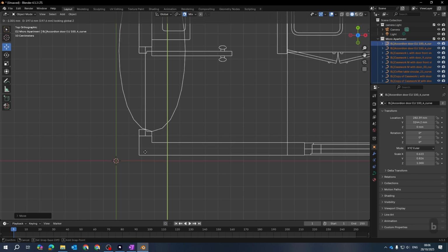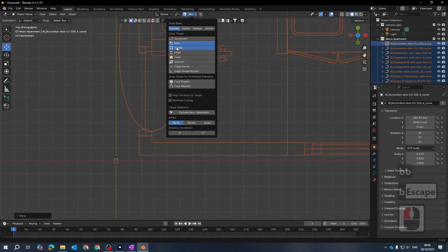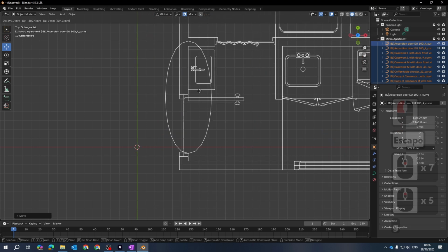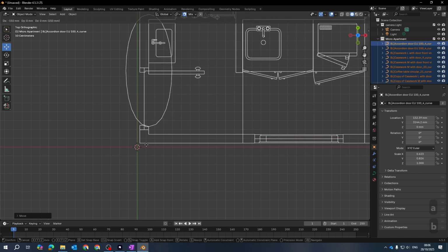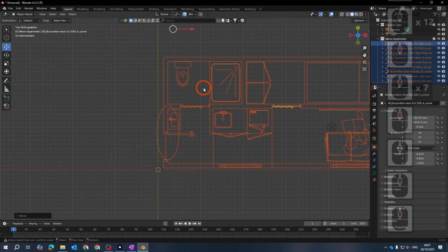So if I go B for base now, it'll ask for a base point, so set base point. I think that's not on, so just make sure. So I want grid and vertex. So I'm going to go to G, B for base point. Okay, so I can snap this information.